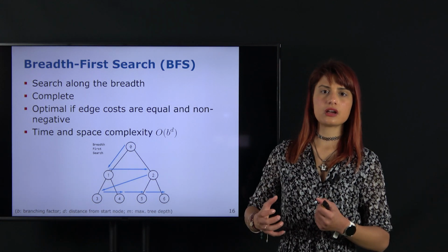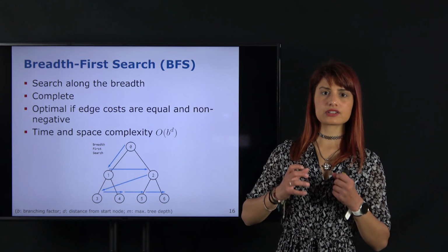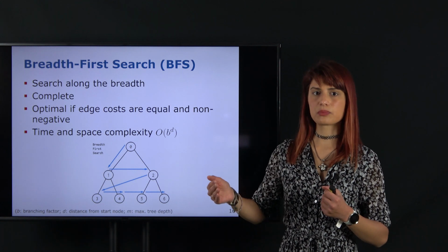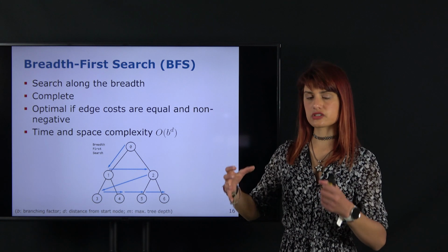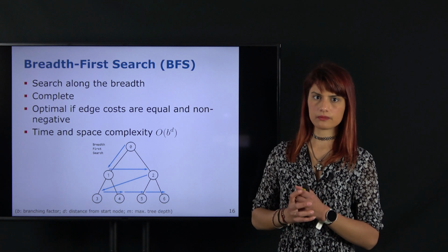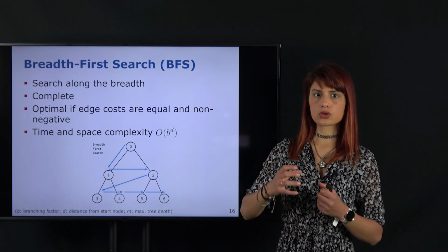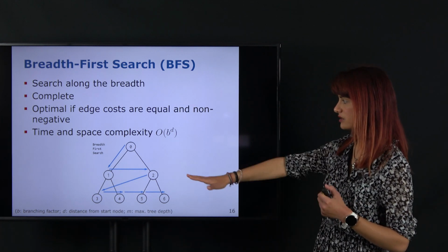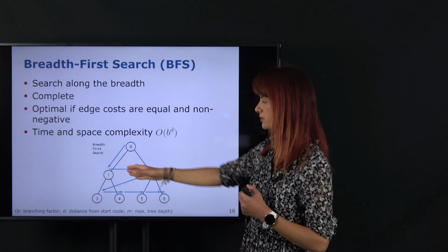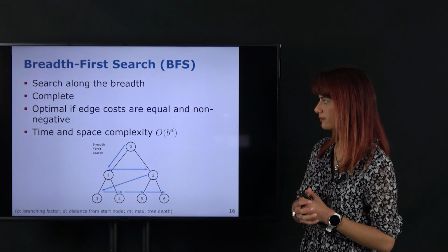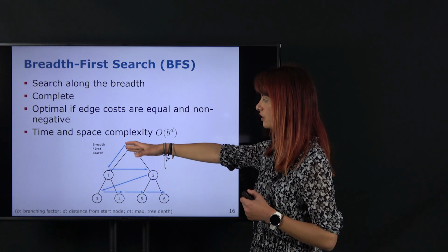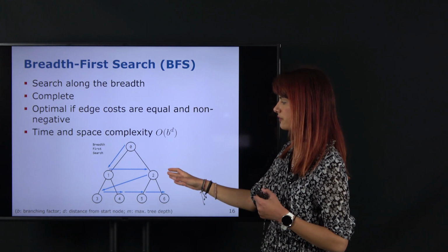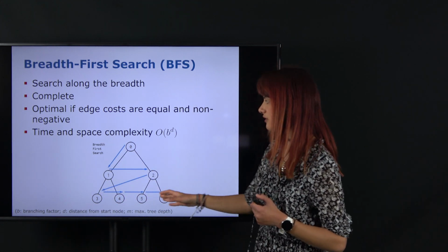So if we start from an initial node or the robot initial configuration, we want to generate all the nodes on a particular level of depth first in the search tree before looking further. So effectively, we're going layer-wise, starting from the initial node. Here's an example where the blue arrows show the order of the expansion. So if this is our root node, our initial node at level 0, we go to all nodes of level 1 first before going to all the nodes of level 2.